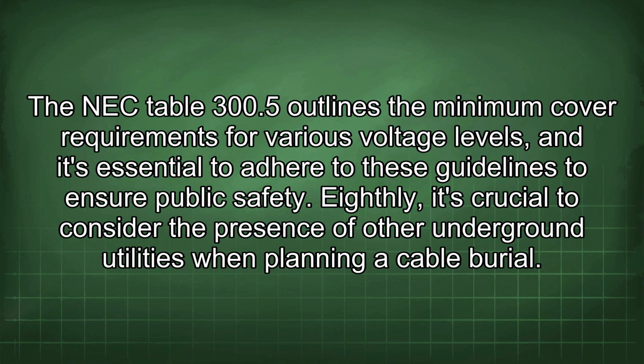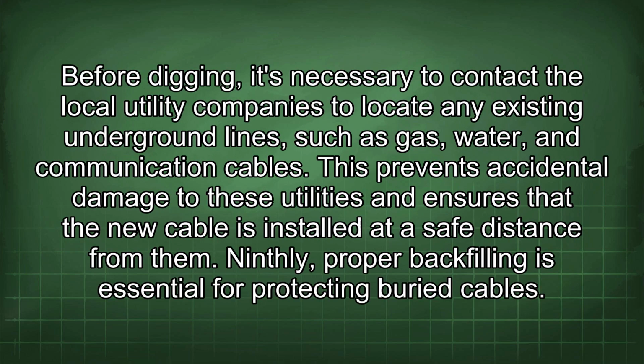Eighthly, it's crucial to consider the presence of other underground utilities when planning a cable burial. Before digging, it's necessary to contact the local utility companies to locate any existing underground lines, such as gas, water, and communication cables. This prevents accidental damage to these utilities and ensures that the new cable is installed at a safe distance from them.